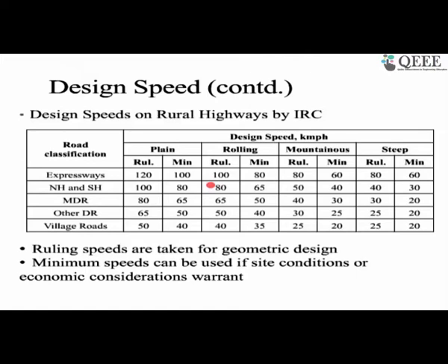You have to decide about the speed and the design vehicle which is going to go through. If you want to put a hairpin bend, and you have a tractor trailer or a multi-axle truck which cannot go through this hairpin bend, then it's wrong. You are not satisfying the design vehicle, so you need to look into the design vehicle. All these aspects are there. So there is nothing out of the blue except the slope stability. Again, geotechnical investigation is needed, whether it is in hilly terrain or any other road.